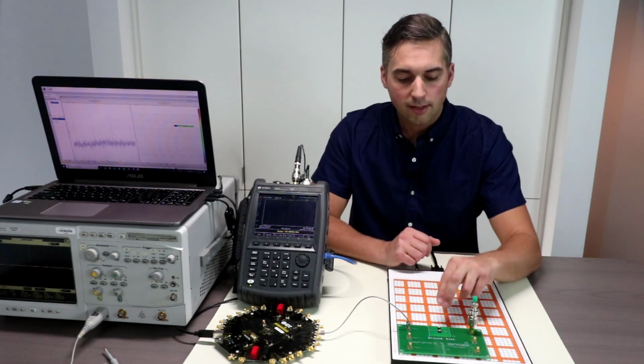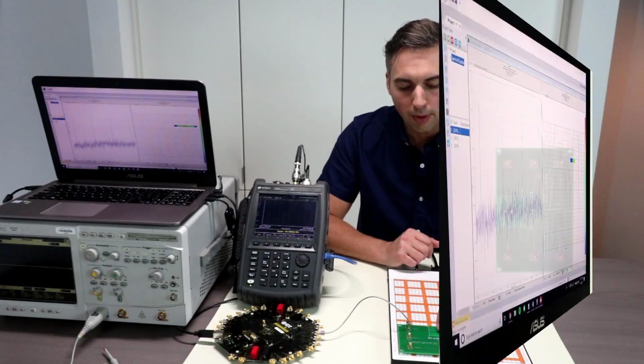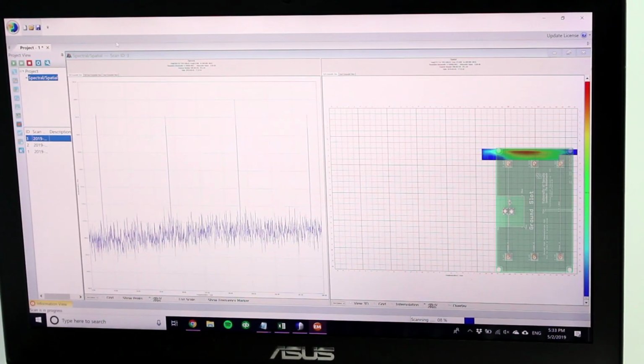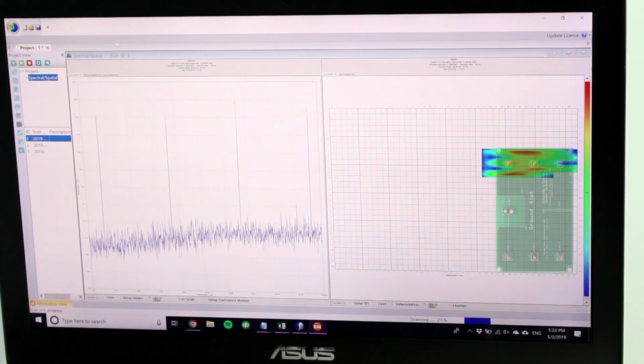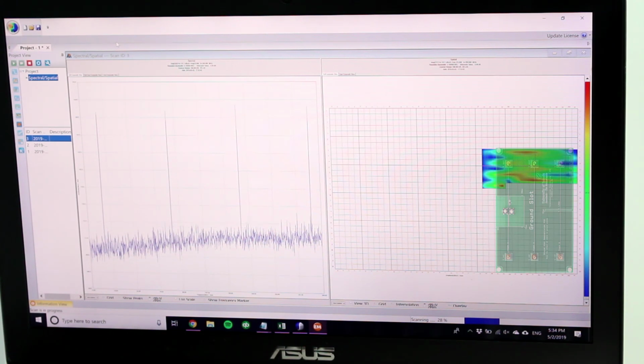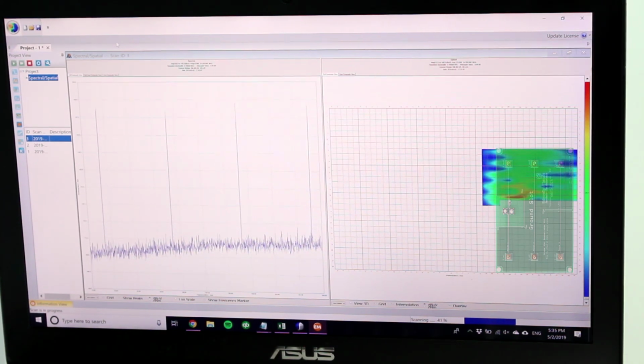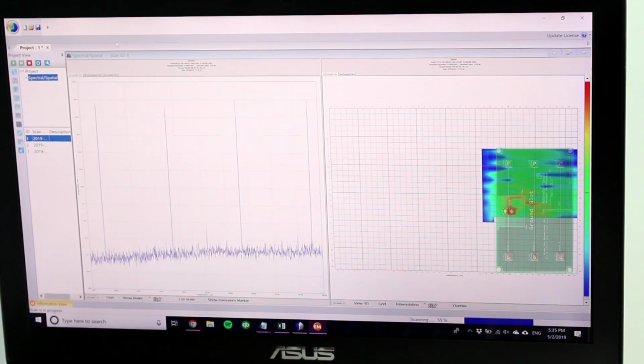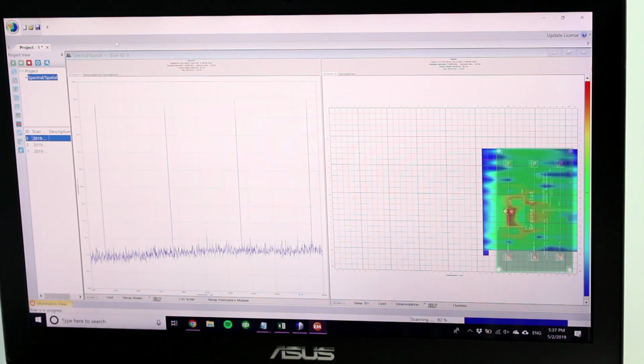Okay, now we're going to run this again, and I'm just going to press these two buttons, which essentially shorts the ground plane on both sides of this. So it's predominantly bypassing the loop that we created. One is a short, the other one is capacitively coupled. So it's essentially two connections from either side, which allows the return current to flow on a much more direct path. So let's have a look at what that looks like in the scan on the EmScan unit.